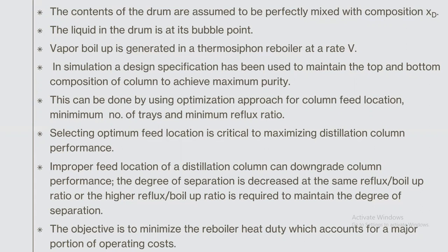So you define what is the purity of your distillate, and usually also define the reflux ratio, because you have 2 degrees of freedom before your system is fully specified. This can be done by using an optimization approach for column feed location, minimum number of trays, and minimum reflux ratio.